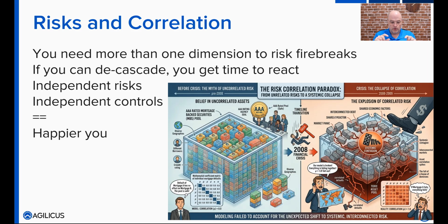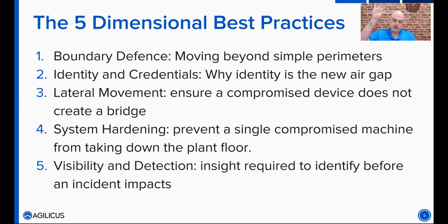So at the very bottom of the floor, you've got a bunch of sensors, and the sensors go into an Ethernet switch, and they're going to go to the PLC. And the sensors, A, shouldn't be able to talk to each other, and B, nothing else in the world should be able to talk to that, even the layer that the PLC's in. And they talk to the PLC. The PLC's got a bunch of stuff going on, so there are controls here and there and everywhere. And it's got some interface up in your SCADA layer and your HMI and so on. And again, it's got a layer there. You don't want the rest of your world getting in and talking Modbus to that thing. It doesn't have a password. So you've got a layer there. And then you've got your HMI, and some other stuff in that area. And then you've got some stuff that supports the process we talked about earlier, VMware, Veeam, all those other things.